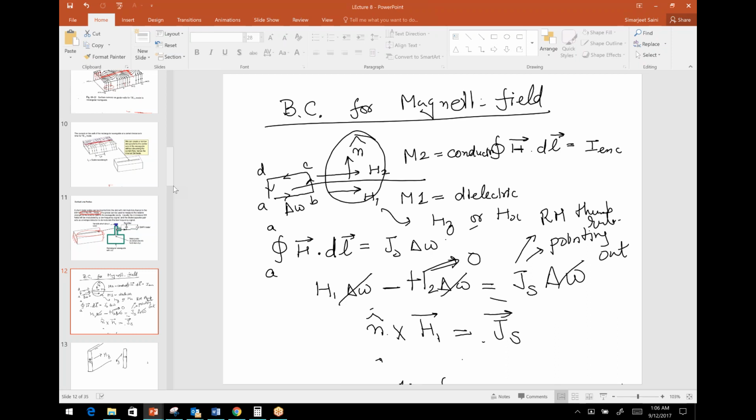And that is the first perturbation we do, saying, hey, the small resistance probably doesn't change the electromagnetic distributions that much. So let's just take the calculations we have for the simple case and use those to calculate the loss, as we had done before for the parallel plate waveguide. Did I answer your question?